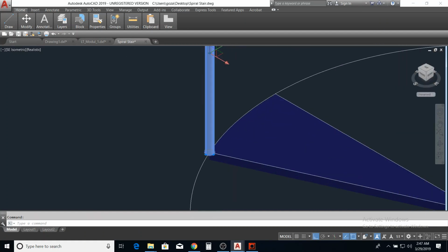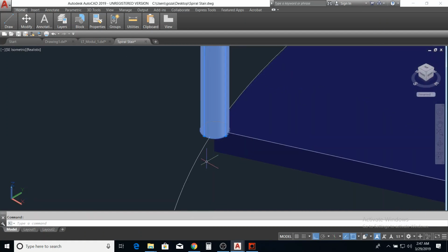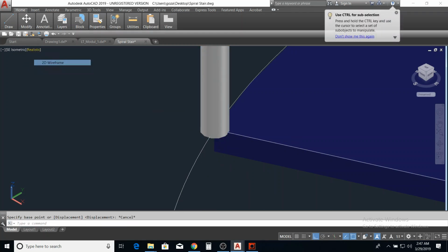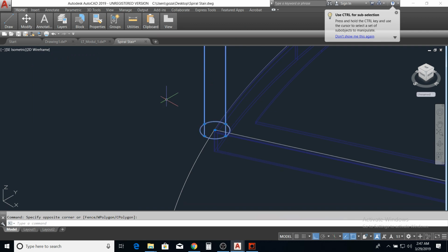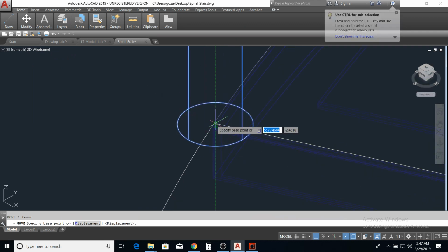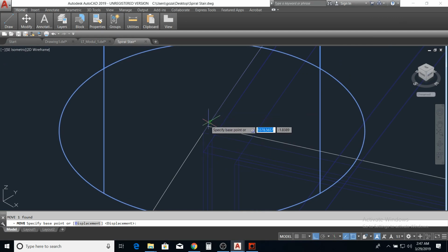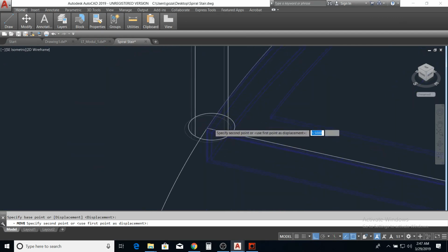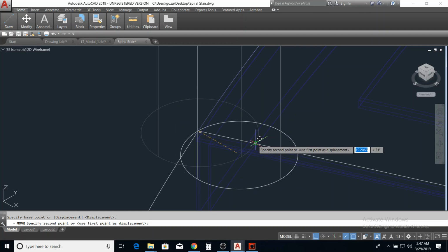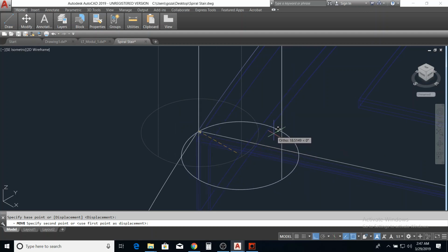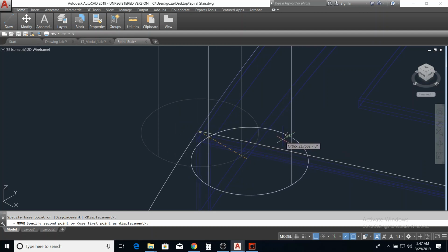What I'm going to do is place this pipe. Better I change the visual style into wireframe a little here for visual purposes. So the pipe is here, side by side. I can move it sideways by 38 divided by 2, 19.